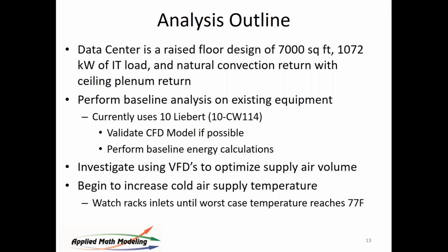We're going to first validate the CFD model if we can. Today we can't because it's a synthetic model. I made it. The point I'm making here is whenever you build a CFD model, you should validate it. If it exists, because in the design phase, they don't exist, you can do this if possible. Go in and make some measurements of what it is you've modeled to make sure your model is predicting the physical phenomena in the room. If it's not, then the model is not going to predict accurately any perturbations that you try to make to the model. The model should be as complicated as necessary and not more.